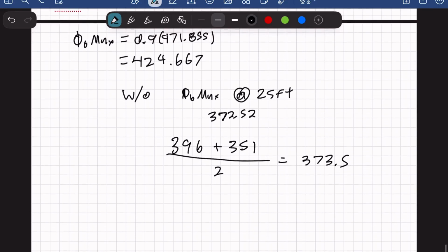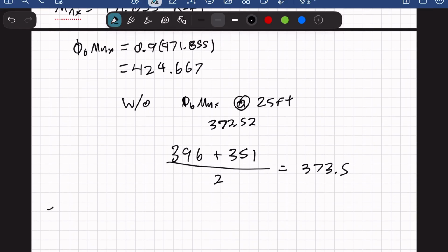So we've gone through this problem. We figured out how to do lambda calculations. We did CB. We didn't calculate CB out by hand, but for this type of problem, there's really no need to. If you really felt like it, you can do the equation for it. I'll actually cover this at a separate time. This isn't really the ideal video for it, because for a uniform beam, you're always just going to know CB is going to equal 1.14 for this case if there's only one support.